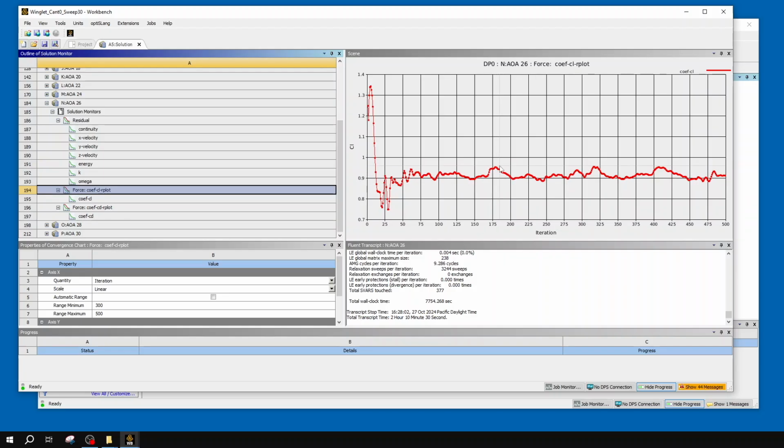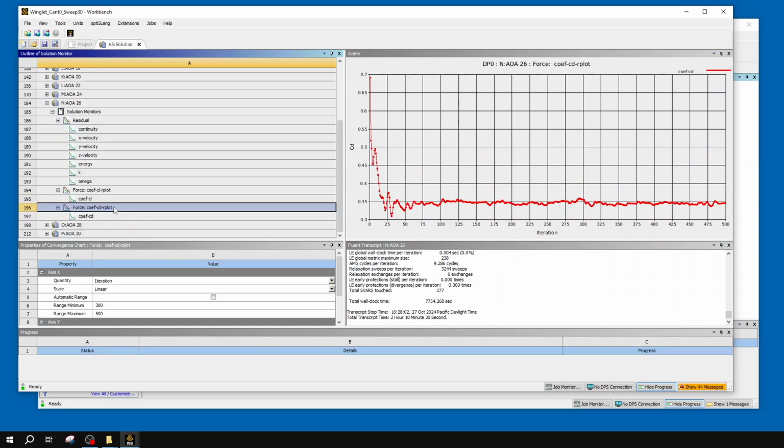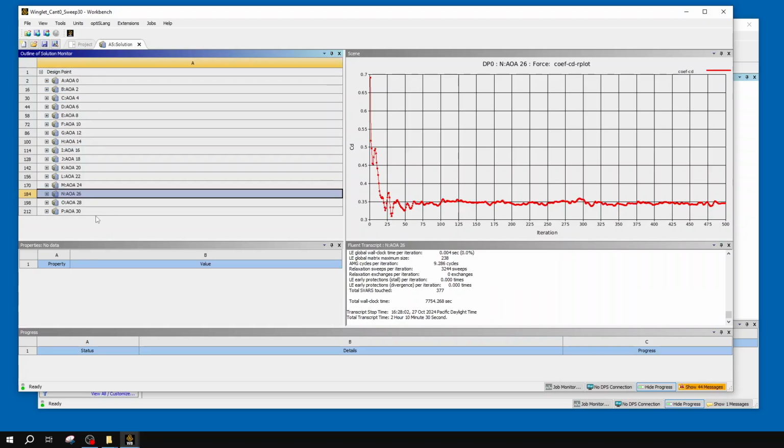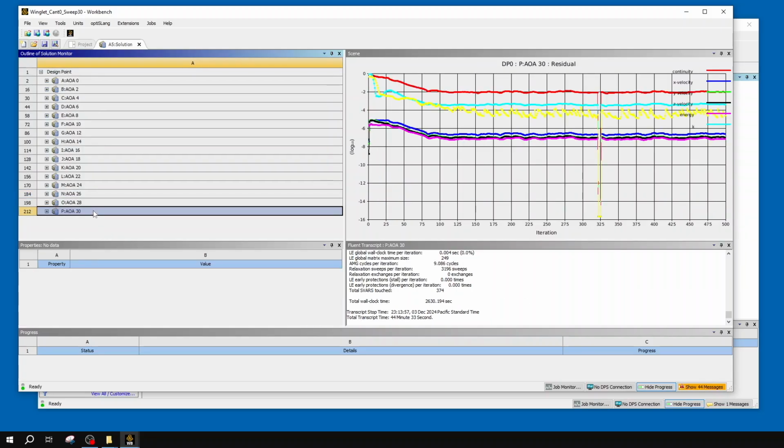So there's no real point in continuing the simulation past this point. It's found a solution, more or less. Same with drag, we see pretty small variations in them. So once you see that, that's another form I accept as convergence, and it works out pretty well for me.